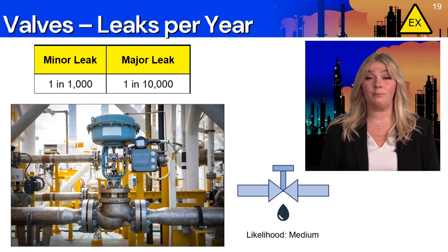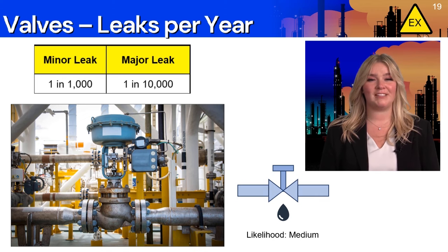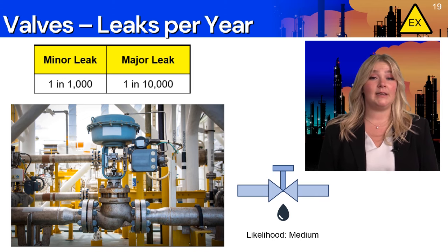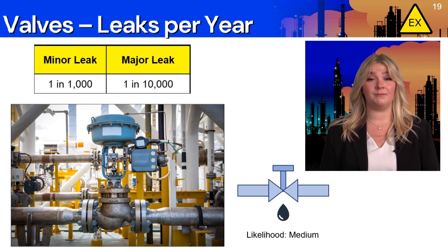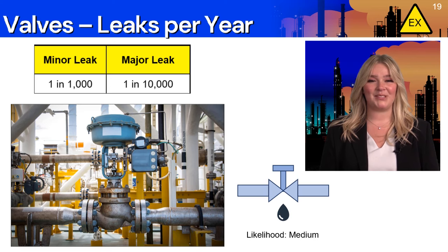Valves that incorporate moving parts will wear with time. The rate of wear is service dependent. Statistically, 1 in 1,000 valves will develop a minor leak in any given year. 1 in 10,000 will develop a major leak. Consider this a medium likelihood.